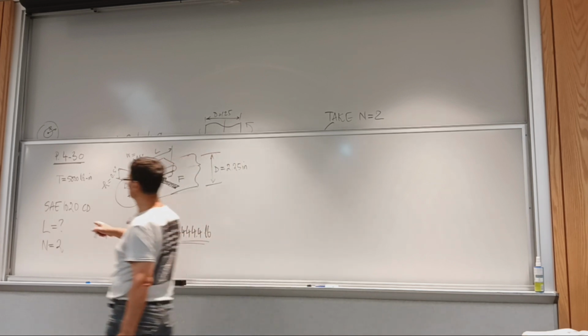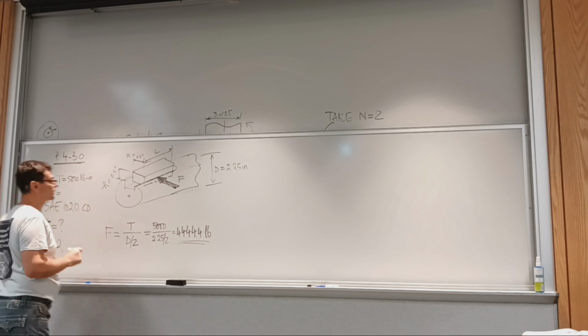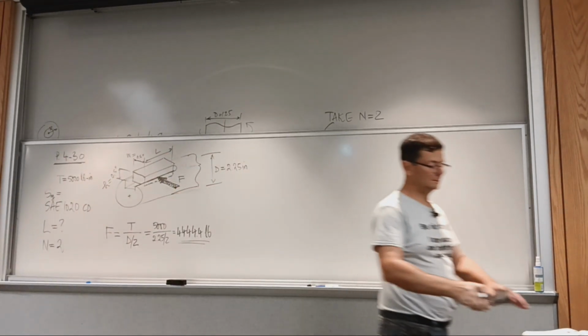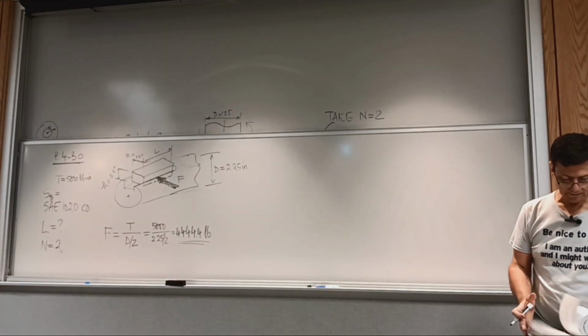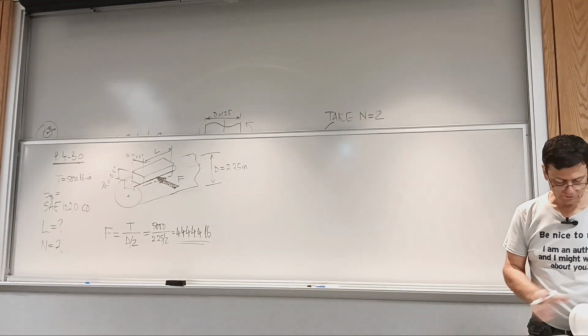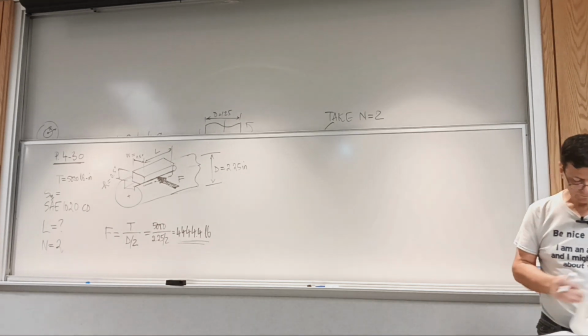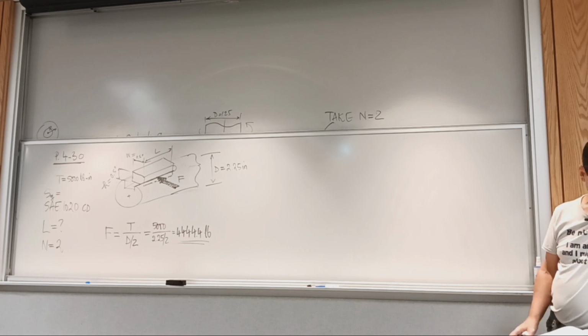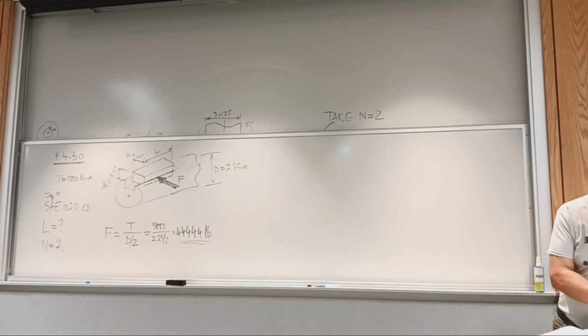We need to find the yield strength in tension for this low carbon steel. We go to the back of the book, where structural steel ends and properties of steel begin. So 1020 cold drawn, 1020 cold drawn.